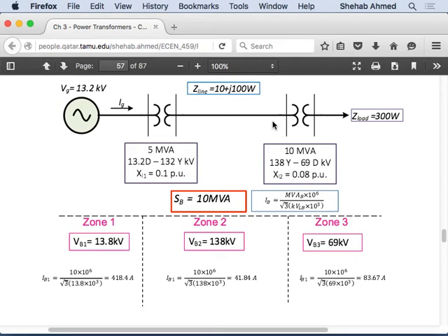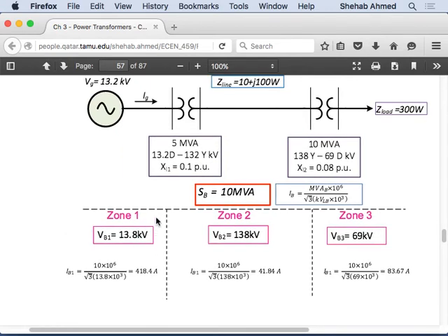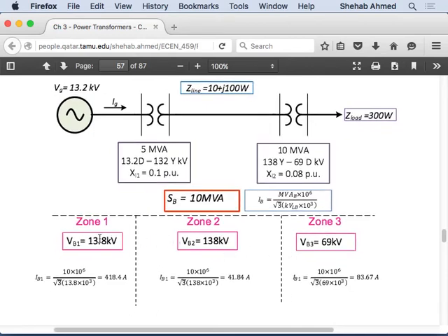From a power rating perspective or power flow perspective, generally, how much power is being consumed by the load from the generator? How much power is being processed by this transmission line? Is this transformer overrated? All of that, I don't care about phase shifts, but we will see how to deal with that. So good point. For now, let's assume that these are two star-star transformers or delta-delta transformers, that they're in phase. Now, divide them up into zones, and then calculate the base voltages.